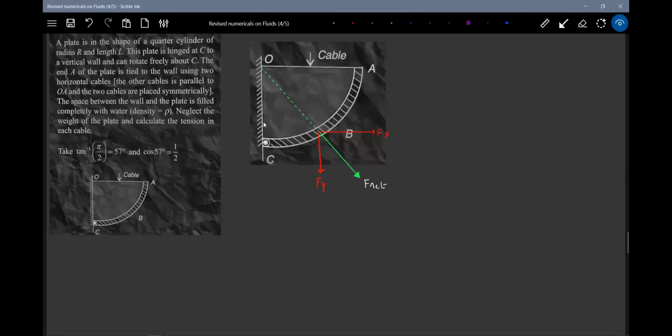Because the liquid will exert force normally, then how this normal force should pass through point O. If you're still not getting it, if you resolve all the forces that you show, or produce them back, all of them will act through the point O. Therefore the resultant force should pass through the point O. The line of action of that should pass through the point O.